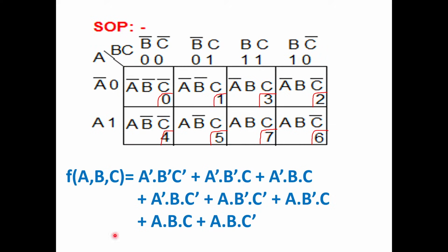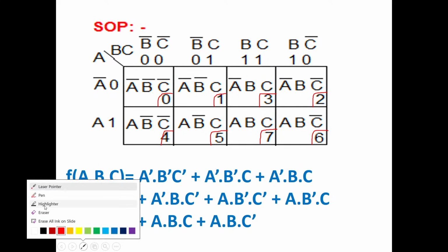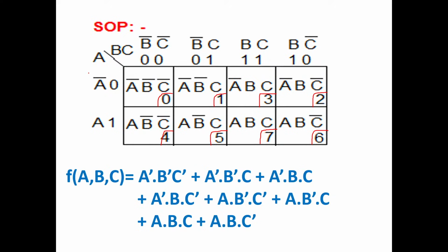There is nothing much to worry about. You have three variables A, B, C. It's a three variable K-map. Write A on one side and B, C on the other side. Now for the first box, write 0, 1. For the boxes above, write 0, 0, next 0, 1.